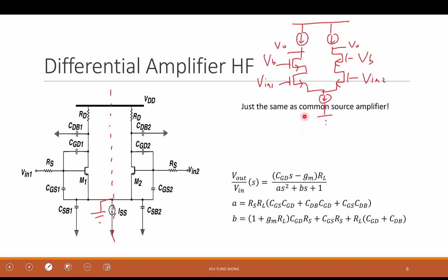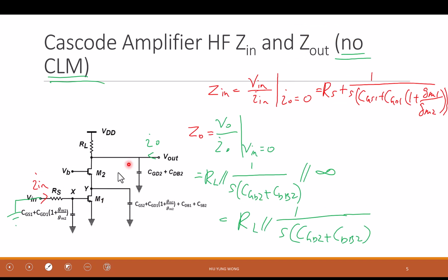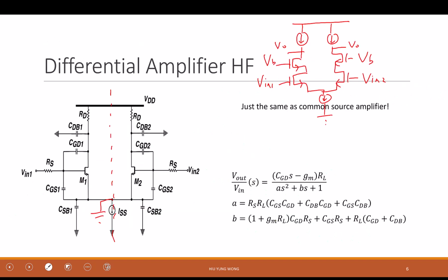This makes sense to you? A differential pair. The left is a Cascode circuit, the right is also Cascode. Again, I can use virtual ground. So this is exactly the same as this one, right? And in that case, you don't have the Miller cap problem because, again, it's only increased by 2 times.